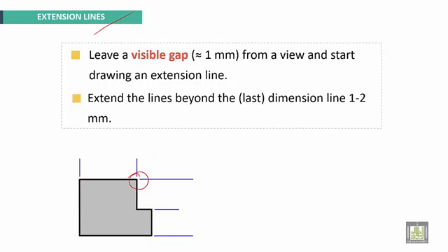Extend the lines beyond the last dimension line by 1 to 2 millimeters. Extend the line here and here by 1 to 2 millimeters. Here also, this small extension.